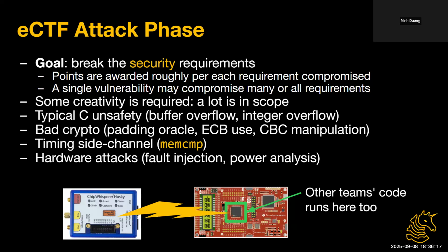As the chip is executing, depending on what data it's executing over or what instruction it's executing, it has a different characteristic for how much power it draws. So again, with statistics, you can get something statistically relevant that will indicate what is happening on the chip or what data it's processing. For cryptography, if it's encrypting something and the power that it draws depends on the key, you can start to figure out what key was used to do the encryption. In the abstract model of what it's computing, you can't figure out anything about the input from the output. That's the abstract idea of what cryptography is. The physical implementation of it has a totally different security profile because it's running in hardware, which can be observed and has physical effects.